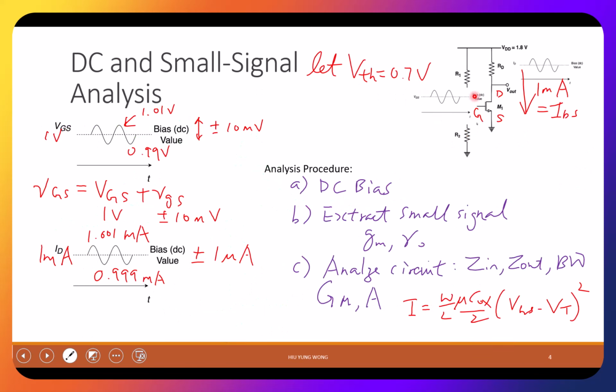To correlate to here, it basically is saying that if this V out is biased at a different voltage in the DC bias, because you can have a small or a large resistance. When you have a small resistance, you have a higher V out, right? Because less potential drop. Then you have a different GM for this guy, in principle.